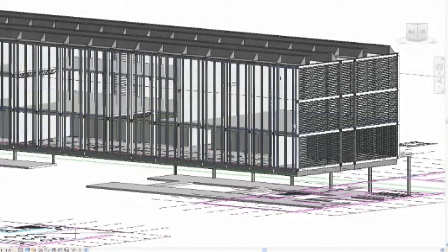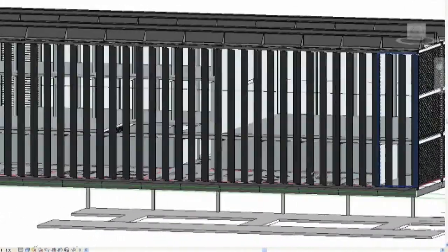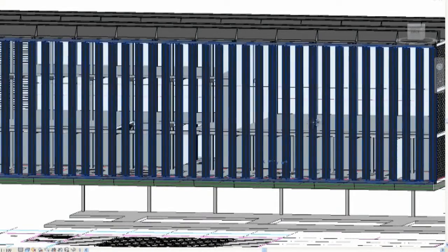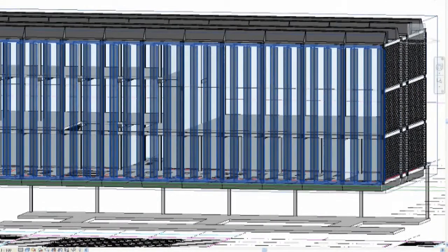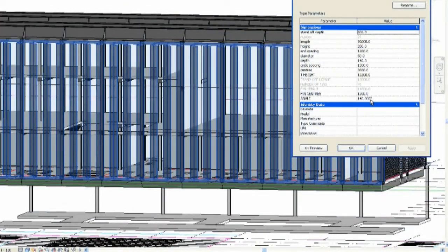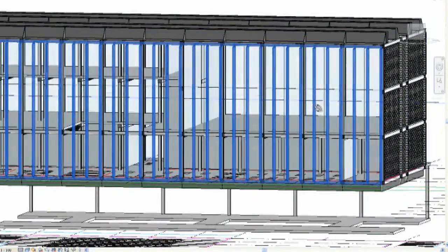Ria created a detailed solar shading model from the information and analysis undertaken during the Vasari modelling phase. By creating a detailed nested family incorporating subframe and brise-soleil, Ria could control the vertical rotation of the solar shading from within the model. She then analysed daylighting and solar gain, and from this evaluated how the elevation could adapt to seasonal changes and resulting sun position.